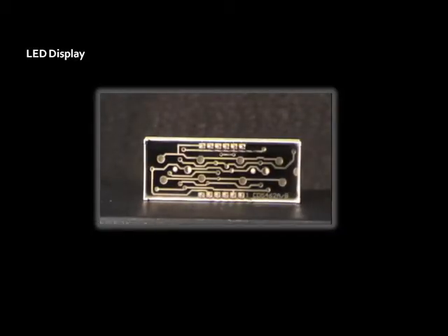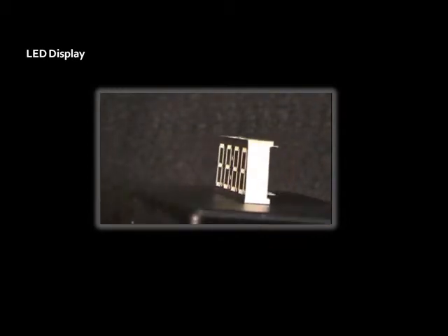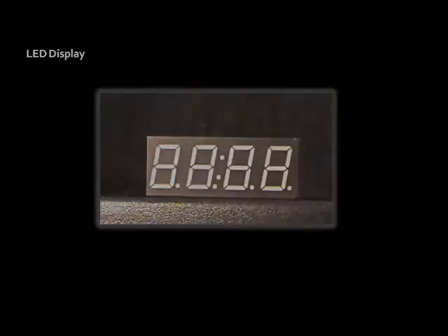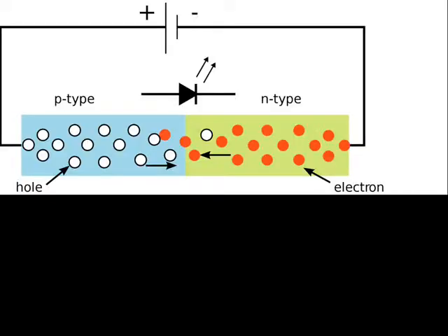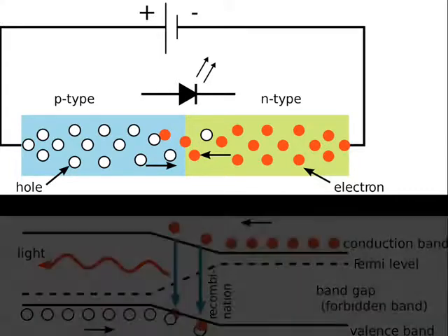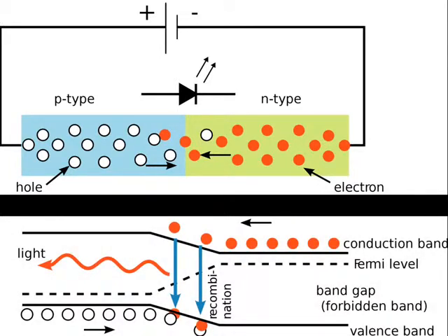An LED display is made of surface mount light-emitting diodes on a PCB in an encasement covered by a lens. Light-emitting diodes are solid-state devices in which electrons emit photons when falling into lower energy levels at the diode P-N junction. The wavelength of the emitted light can be selected to achieve nearly any color in the visible spectrum and even non-visible spectrum such as IR.